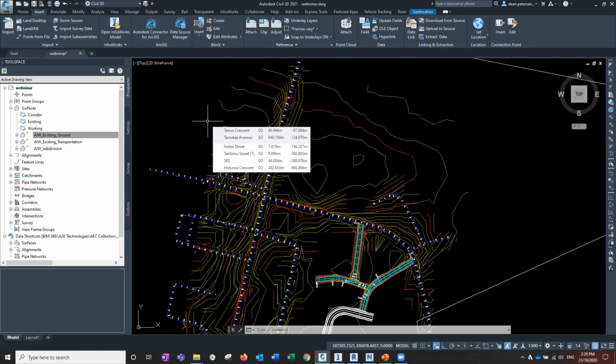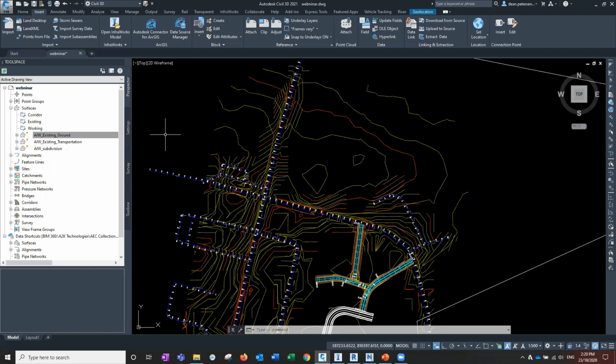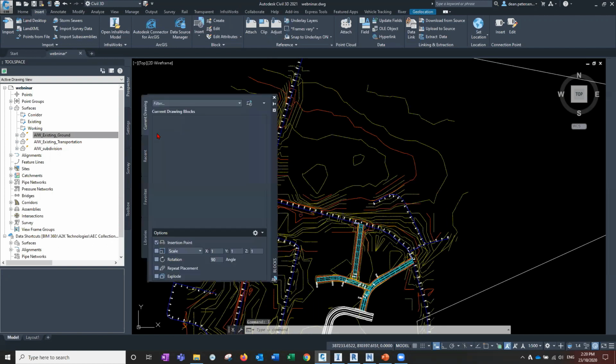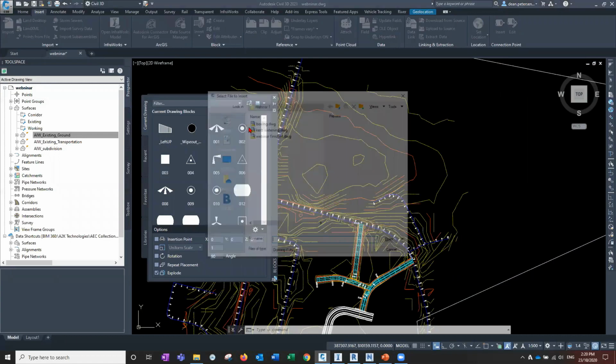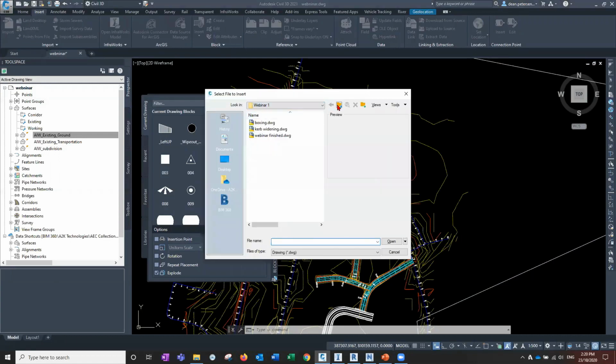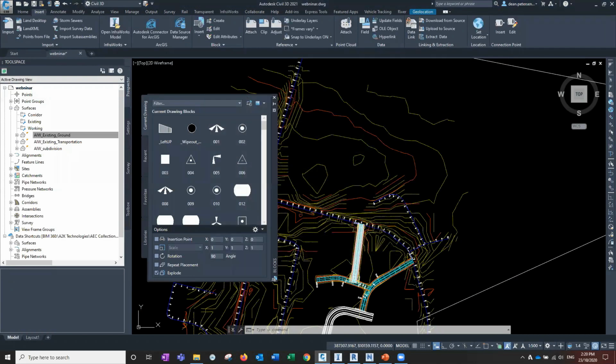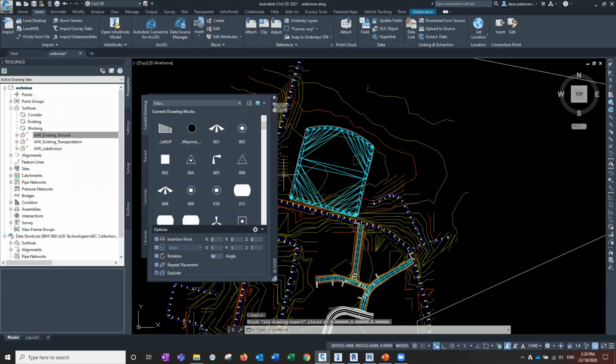So in this particular model, we can go and insert. I enter an insert command, just the AutoCAD insert. Now we don't want to change its positioning. It's in the same survey coordinate system already. We want to explode it so its individual components, and we will click this button here to go and search for it, and it is under webinar 2, start files, 12D drawing export. Okay, so having selected that, it just jumps straight in.